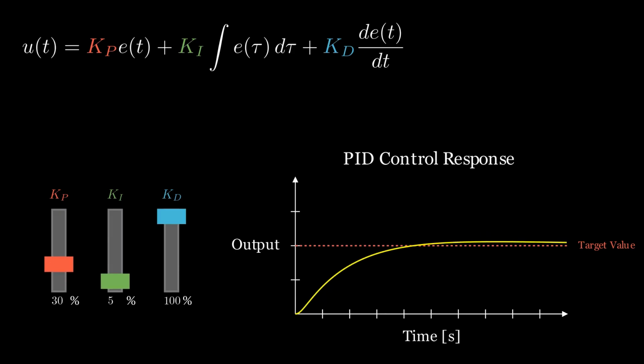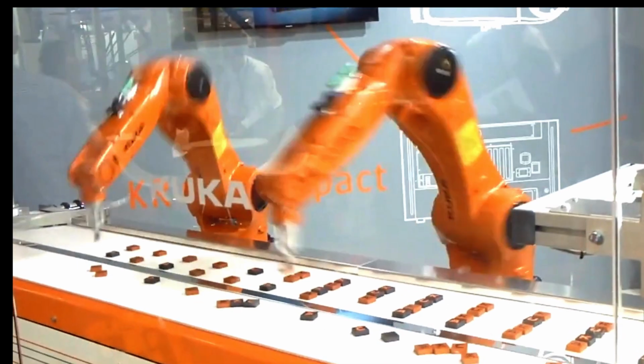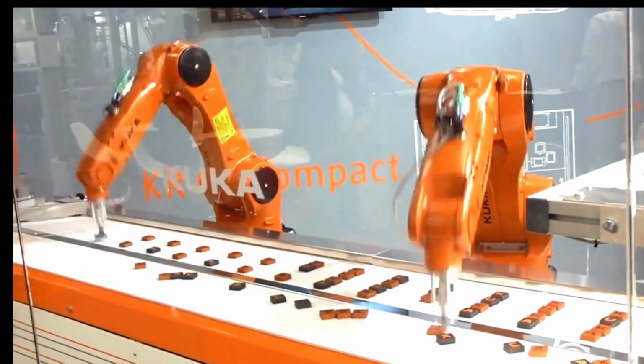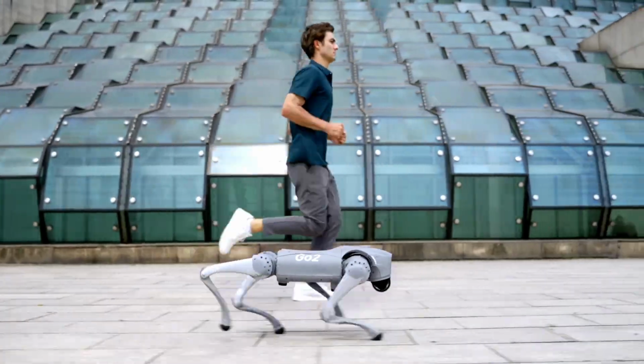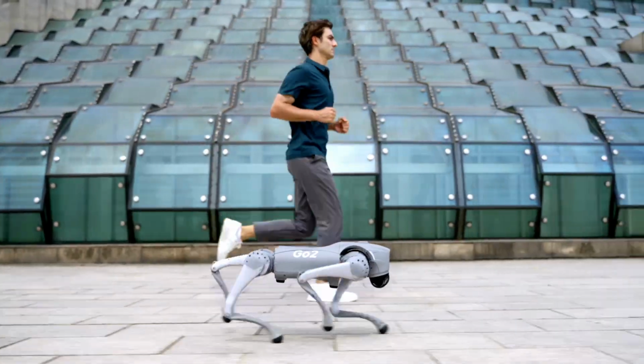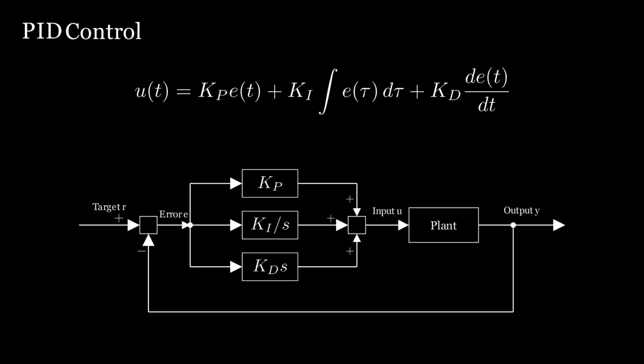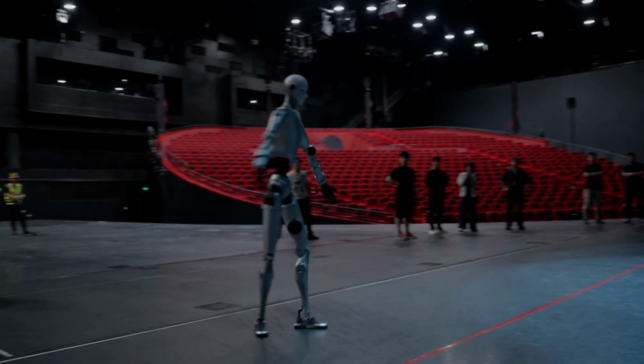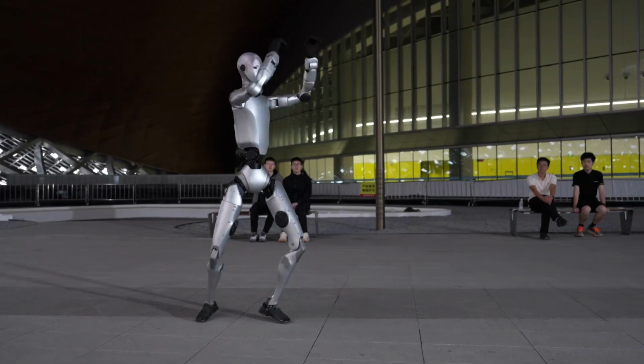For the Go-To, if you increase P gain too much trying to move the legs quickly, the whole robot becomes unstable and could potentially fall. So simple PID alone has its limits, as suggested. PID works well for simple tasks like maintaining joint angles, but it's conceptually insufficient for dynamic walking. Why is that again? Because PID is merely a reactive controller that responds to past and current errors. It has no predictive capability to coordinate the robot's overall movement, like determining how it should move in the next moment. Given these limitations, more advanced control methods with better system understanding become necessary.